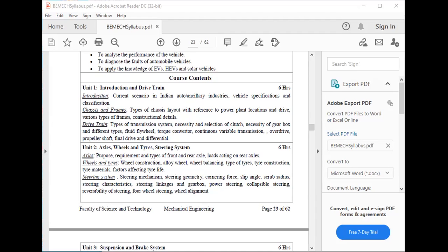If we see the types of clutch according to the conditions, there are wet clutch and dry clutch, these are the two different types available. Wet clutch is immersed in a cooling lubricating fluid which also keeps the surfaces clean and gives smoother performance and longer life. Wet clutches, however, tend to lose some energy to the liquid. The dry clutch, as the name implies, is not bathed in fluid and runs dry.